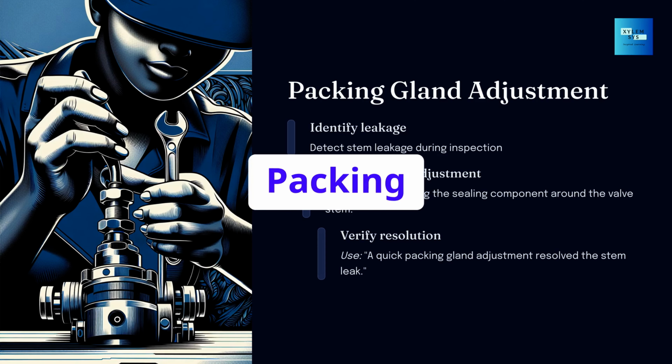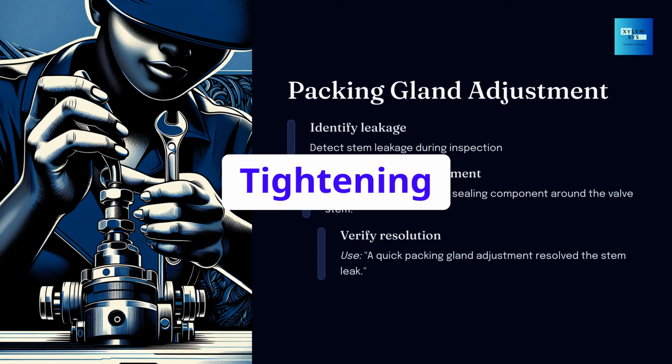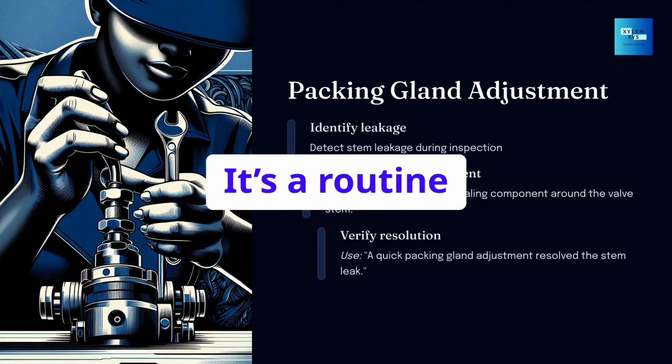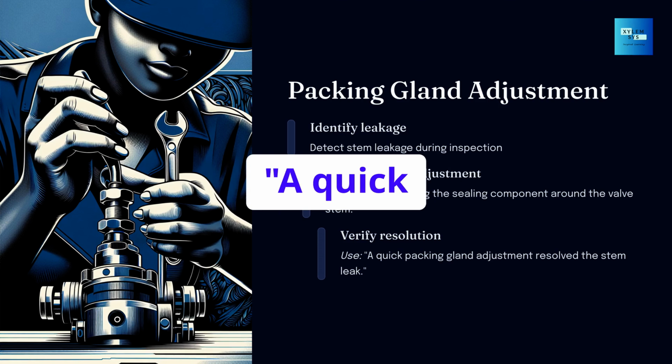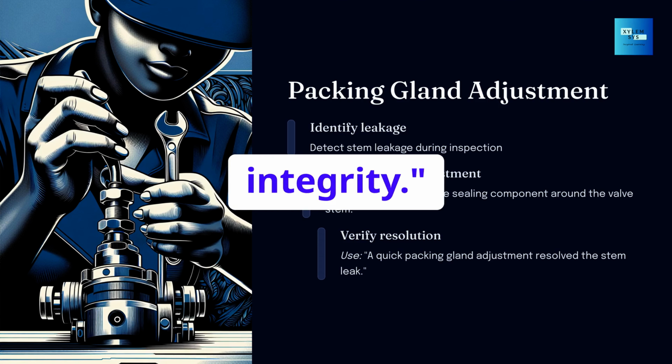22. Packing gland adjustment. Tightening the packing gland ensures a leak-free stem seal. It's a routine maintenance task. A quick packing gland adjustment resolved the stem leak and improved sealing integrity.